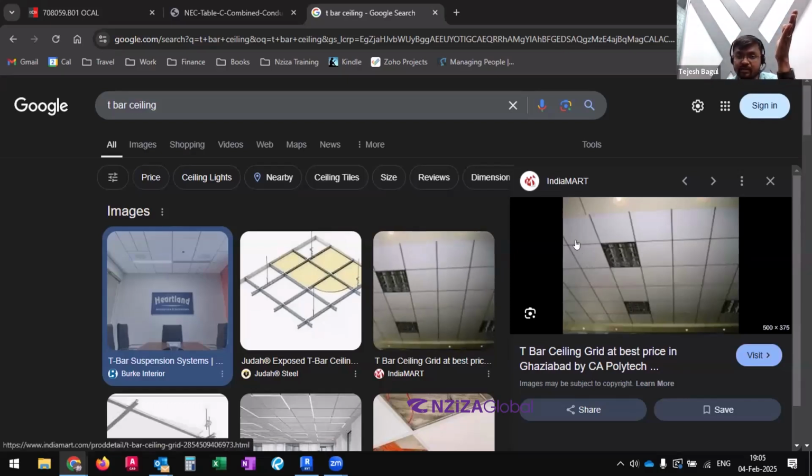So in case the path of egress is going, let's say, somewhere from this 3rd tile on my screen over here, then it would be better to have the light fixtures on the other side, one tile to the left. So that is how you will determine the given spacing and layout of the light fixtures.